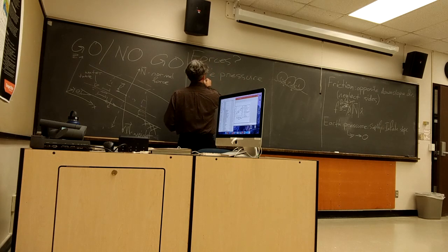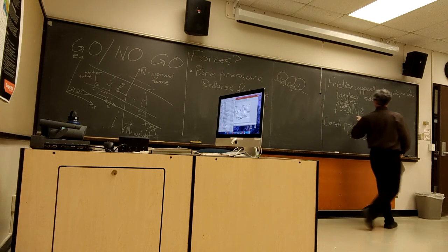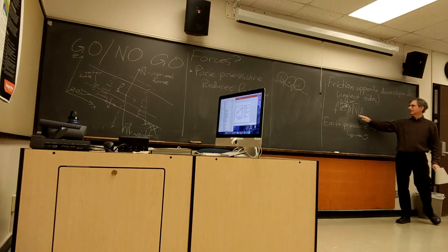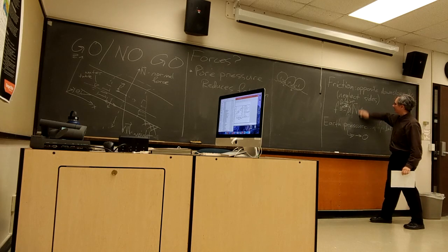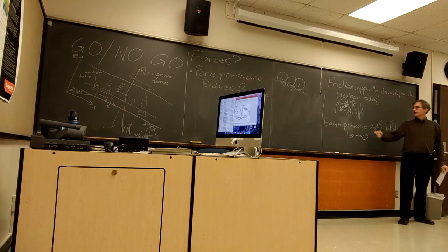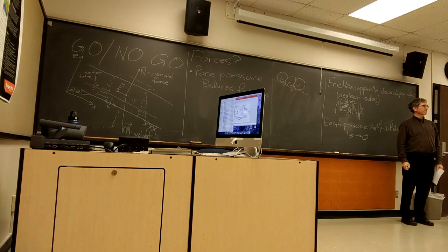So the effect then is, since my friction force is proportional to the magnitude of the normal force, well, actually, I should put a caveat on that and put a little effective down here, because in order to get my friction, I have to subtract the pore pressure.